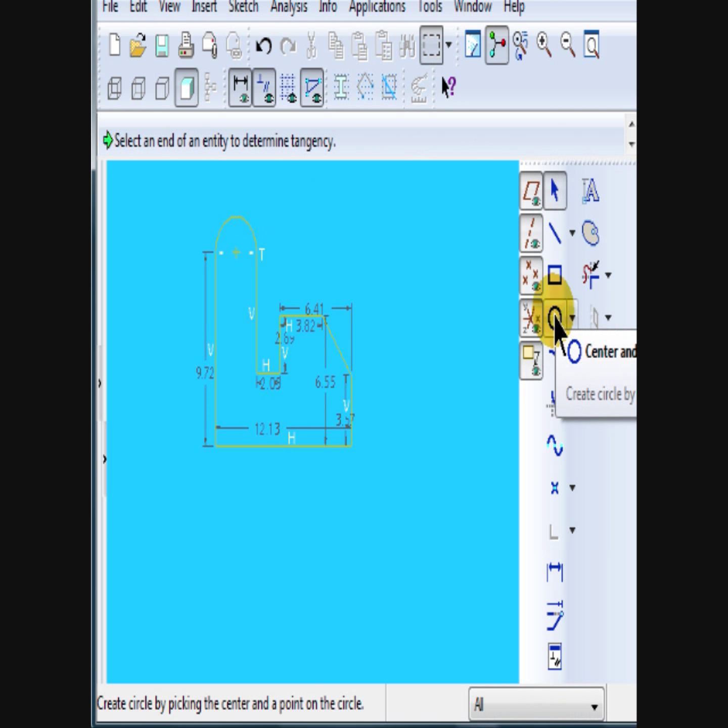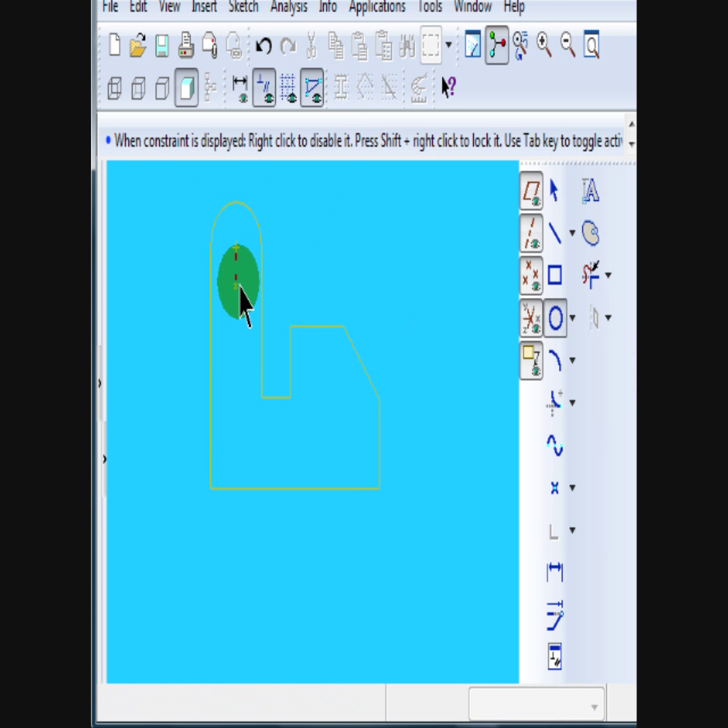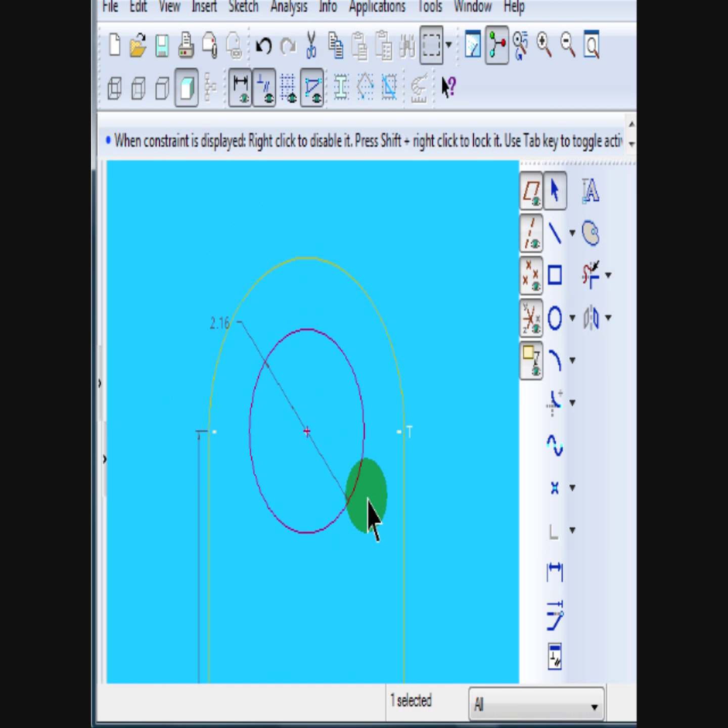Now to draw the circle, we're using the same center for the arc. So that's your first click, left mouse button. Stretch it, and another click. That would give you the circle. Refit screen so you can see the whole part.